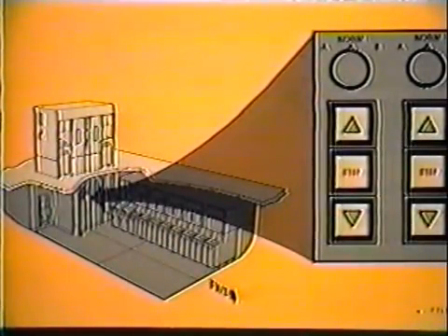The lower galley lift control panel has the same directional control switches as the upper panel. In addition, it contains motor selectors. 2 motors designated A and B drive each lift. Should one motor fail, the operating motor should be selected. The lift will operate at half speed. It takes approximately 7 seconds travel time between levels with both motors operating.